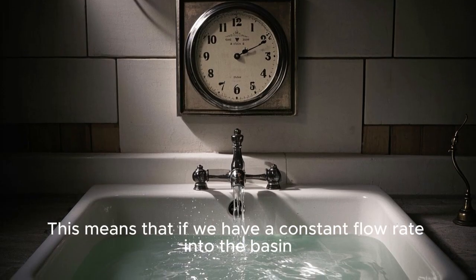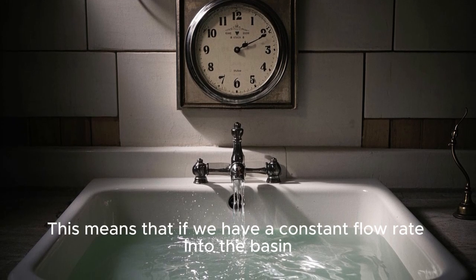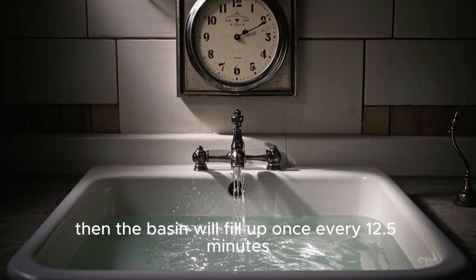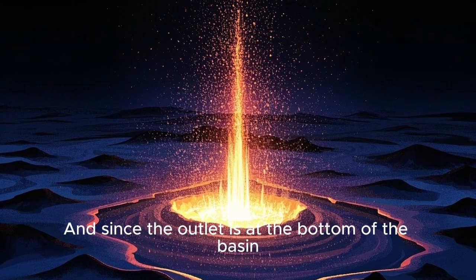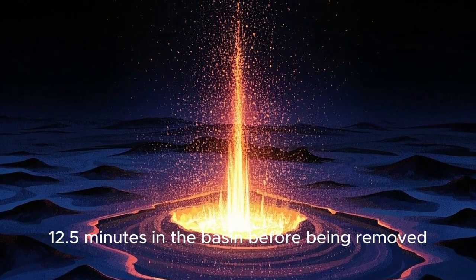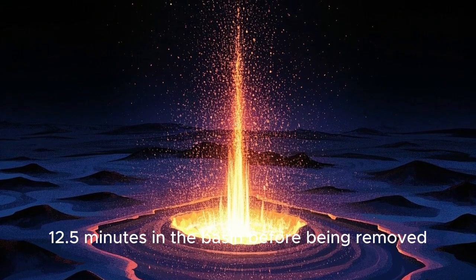This means that if we have a constant flow rate into the basin, then the basin will fill up once every 12.5 minutes. And since the outlet is at the bottom of the basin, this also means that the average particle will spend 12.5 minutes in the basin before being removed.